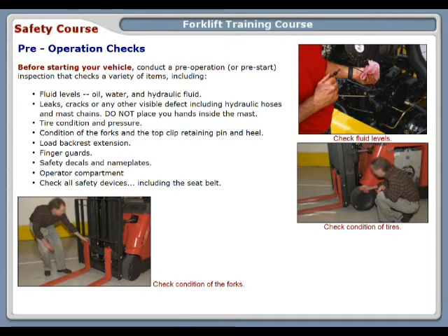Before using your forklift, be sure to conduct a pre-operation or pre-start inspection that checks a variety of items, including fluid levels for oil, water, and hydraulics. Check for leaks, cracks, or any other visible defects, including hydraulic hose and mast chains. Don't place your hands inside the mast. Check tire conditions and tire pressure.